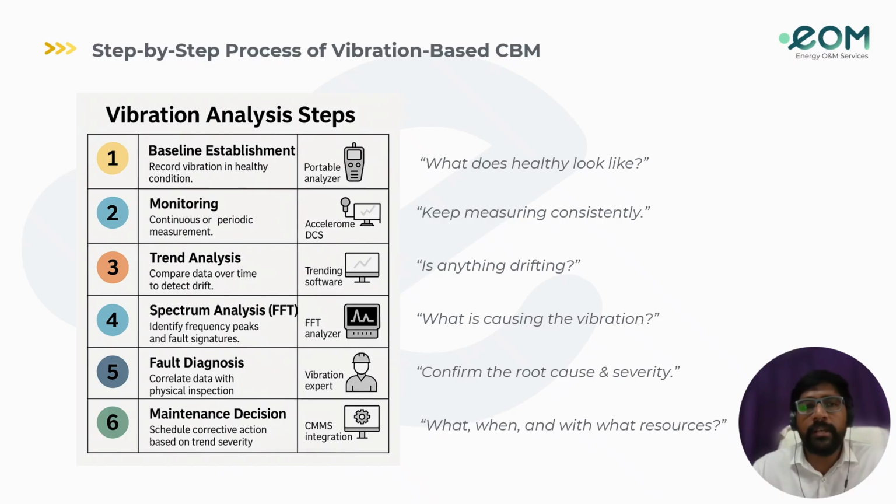First thing we'll do is baseline establishment, meaning creating the reference signature for each machine, noting the operating conditions like operating speed, operating load, and ambient conditions. The next one would be mounting, where continuous online monitoring or periodic monitoring is done, meaning weekly or monthly monitoring. Same measuring points, same orientation, same operating conditions. We should log the route order and use machine tags or QR codes. Those are the main good practices for this.